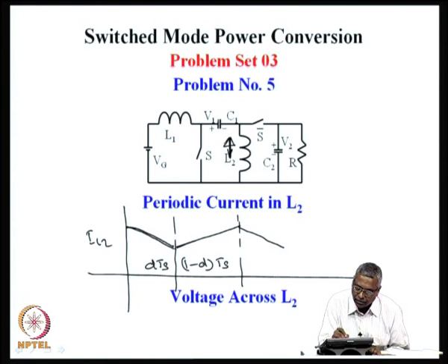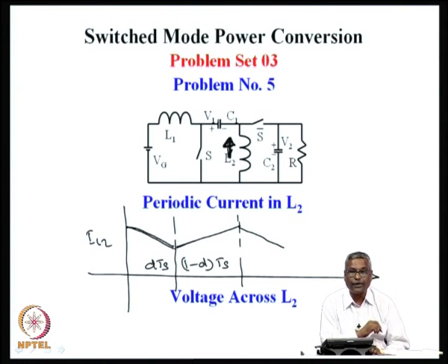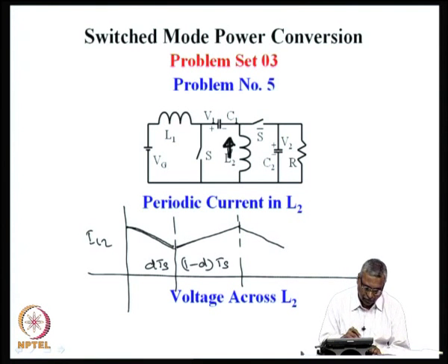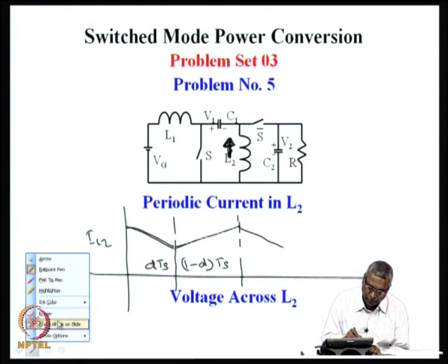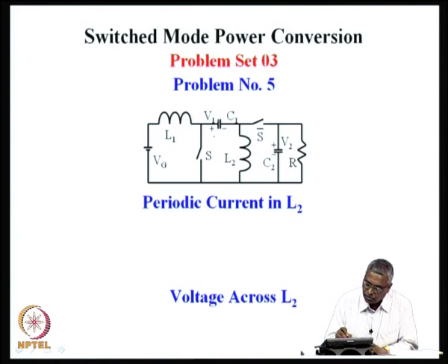Inductor current is in this polarity. So, when the switch is on, inductor current is rising in the polarity shown here with arrow, and when this switch is off, in this polarity it will be falling. Let me draw that correctly. This is always fine. So, the inductor current now I will show in this polarity, in this direction. This is the direction of the current, and it will go and charge this.